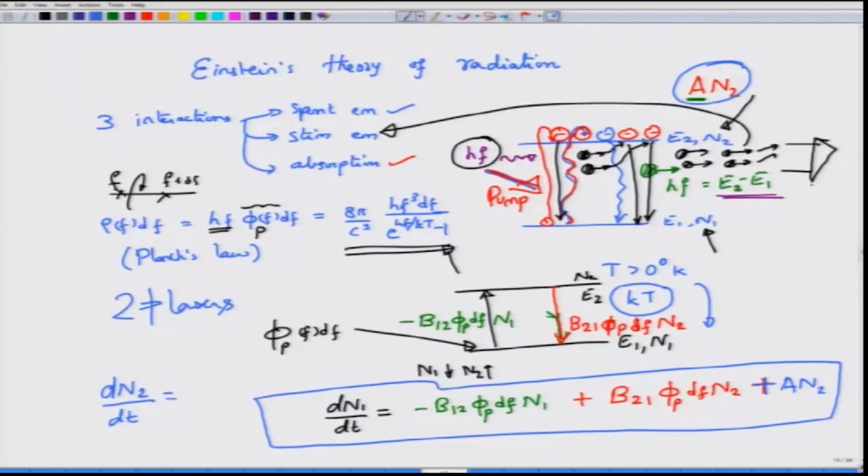Even the semiconductor injection laser diode is also a 4 level laser, but for some applications or with some simplifying assumptions, we can treat the 4 level systems as 3 level systems. So, 3 level is the minimum required level for lasing, and it is also applicable with some approximations to the more practical 4 level systems, and we will of course look at 3 level systems.